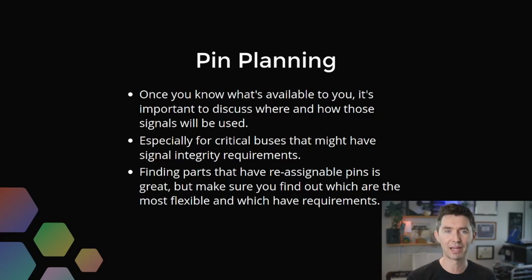And again, trying to minimize that disruption, because once you make some of these decisions, it becomes hard, not impossible, hard to backtrack. And if you do, I am very, very encouraged by all of the chip vendors that are out there that are making GPIOs much more flexible. They kind of have these crosshatch kind of ability to reassign pins. That is amazing, but some of them always have these kind of little asterisks up in the corner, and make sure that you understand where there's an asterisk, because that can be problematic for your design.